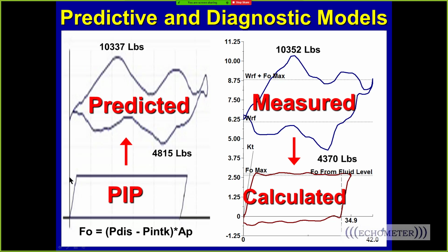and then we calculate the downhole stroke. And we can do either anchored or unanchored tubing, whereas with the measured diagnostic software like TAM and T2M, we measure the surface loads on the upstroke and on the downstroke, and that we call an acquired or measured surface dynamometer card. And then we use a wave equation to calculate the effect of the dynamic motion down the rod string with the properties of the rods. And when we get to the end of the rod string, what's left over at the end of the rod string, we call that the pump card,